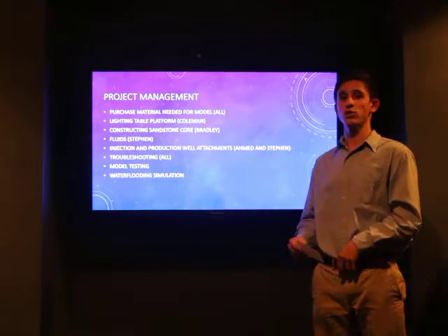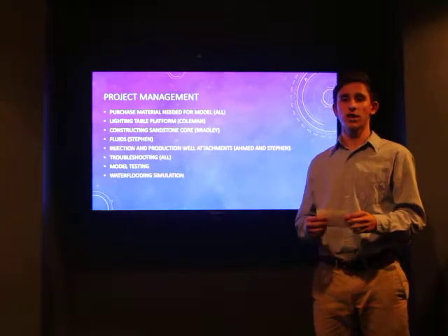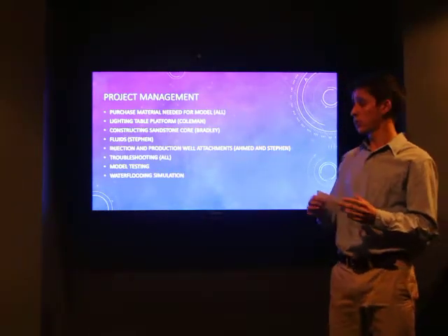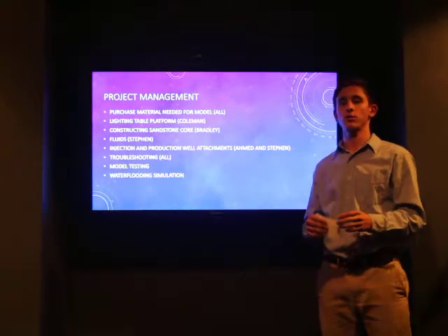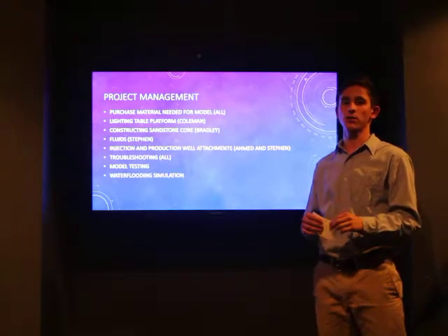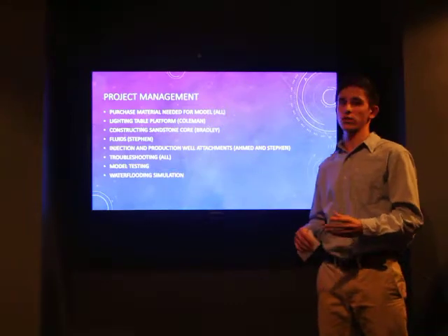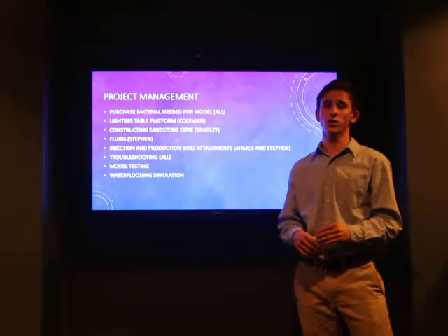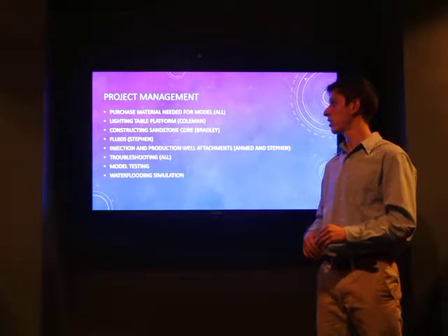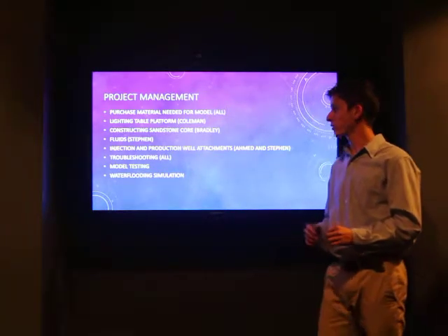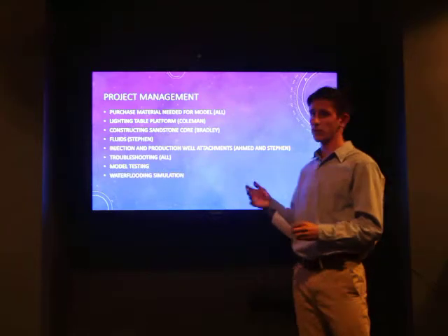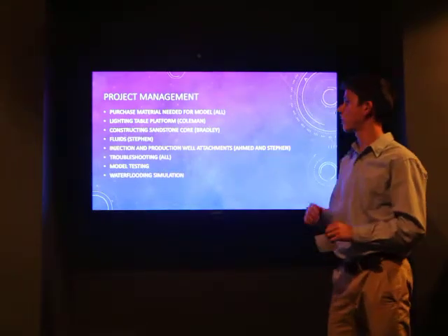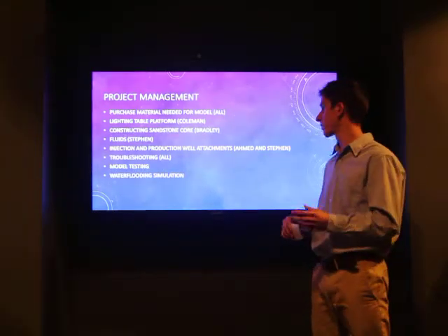The reasoning for choosing these two fluids is that they are miscible in all proportions, and this produces a constant effective permeability throughout the displacement process. Therefore, the mobility ratio would just be the ratio of the viscosities. To inject these fluids into the core, we have tubing and injection and production valves.